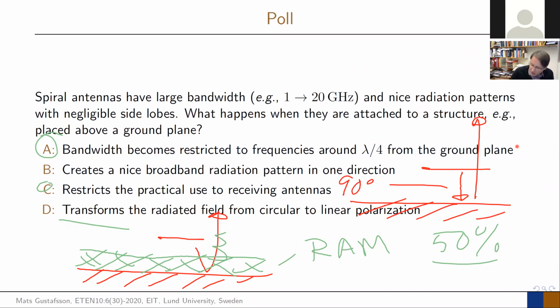And that means that when you go up there, there is another 90 degrees. And if you add 90 degrees and 90 degrees, you have 180 degrees. So it's totally out of phase. But what's happening is that when this wave hits the ground plane, in this precise reflection there, that is another 180 degrees. So you get 90 degrees from the propagation, lambda over 4. You get 180 degrees from the hit in the ground plane, and you get another 90 degrees with radiating out.